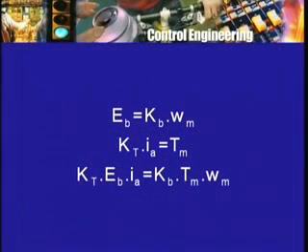That is, if one looks at the motor from the electric aspect, there is the back EMF Eb, which is very nearly equal to Ea, multiplied by the armature current. The electric power is equal to, if you look at the mechanical side, a torque Tm and rotation at omega m speed, and therefore a mechanical power Tm into omega m.